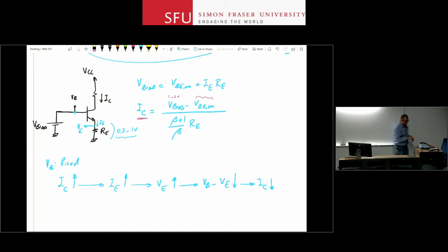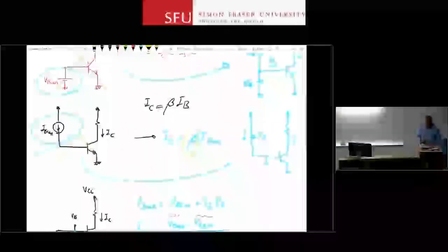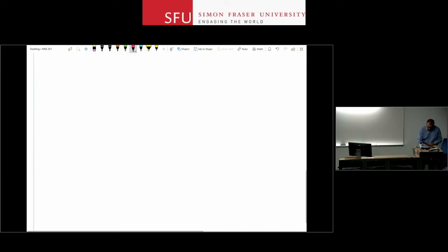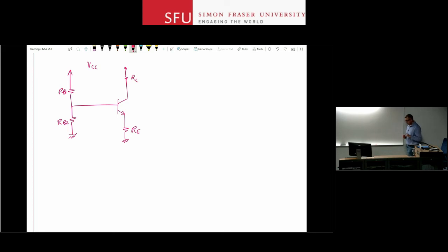Right? And, now at this point of time, knowing all this stuff that we mentioned before, here is what I can do. I can go and use a resistive network to get the bias voltage that I need, put a resistor here to get the bias stability, the internal feedback mechanism in your circuit, and over here you may or may not have a resistor. I'm not really concerned too much about the collector terminal at this end. As long as the device is in active region, I'm happy. I just want IC. Okay?